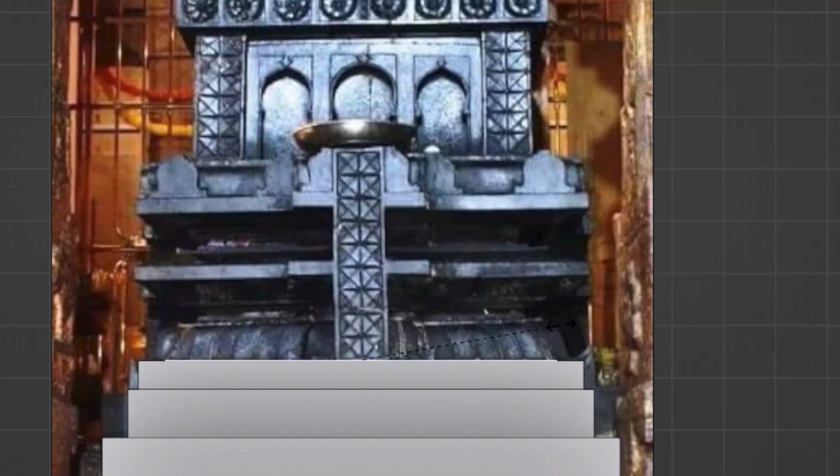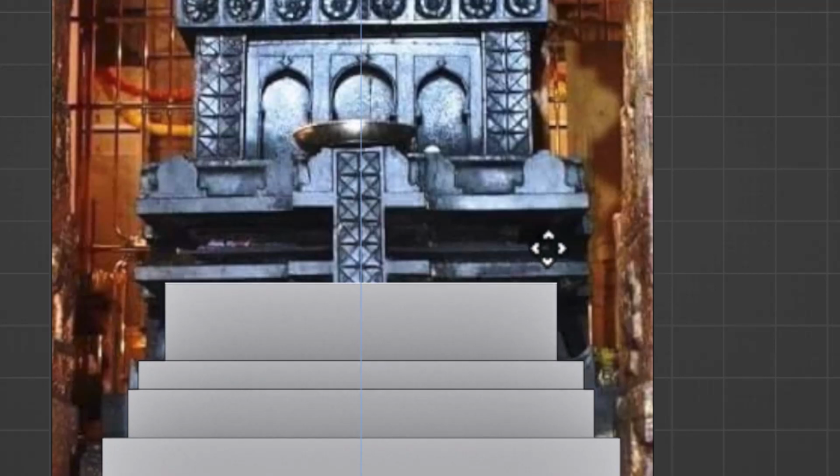Once you have already done the inset, change it using scale, and after this I will press E again and move it to the top till here. The other remaining details we are going to add in our future classes. Then now here I have to increase the size. Remember, in inset you cannot increase the size, you can only decrease the face, but you cannot increase the face.